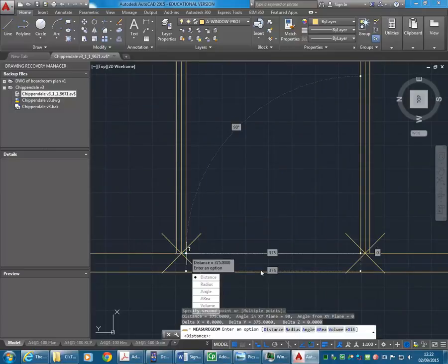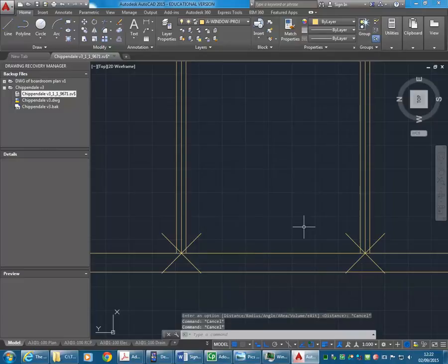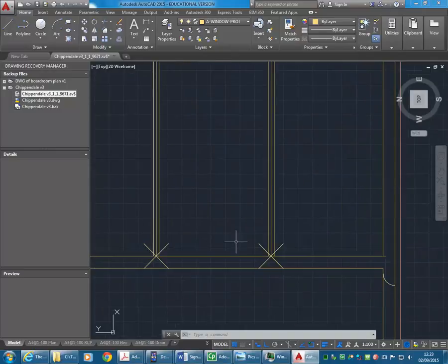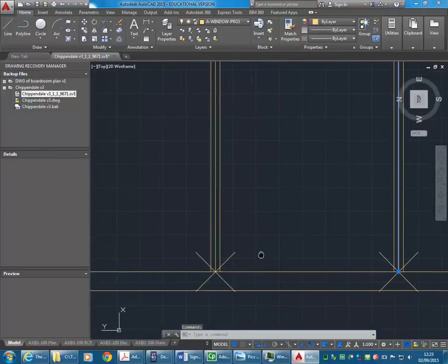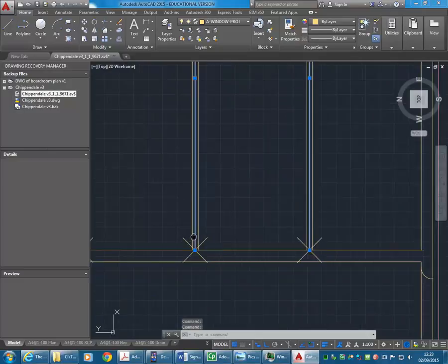And that might help you when you're doing your set-outs generally, because when you need to draw, say, folding doors or cupboard doors or kitchen cabinets, they need to all be even. And it's not just that you measure when you're measuring from the ends, but you'll often have things that have a frame where the frames need to be positioned evenly along another span. So you need to understand that set-out process.